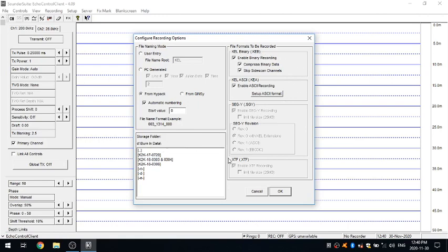The other option we have here is the different file formats. There's two main ones, the KEA and KEB. The KEB stands for Knudsen Engineering Binary, and the KEA stands for Knudsen Engineering ASCII. With the Knudsen Engineering Binary, basically that's just recording your echogram. All the data that you see scrolling across your screen, you can record that and then play it back afterwards and view it in your post-survey application.